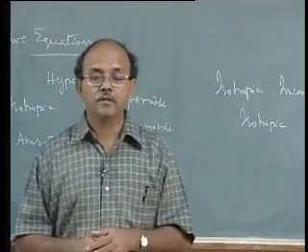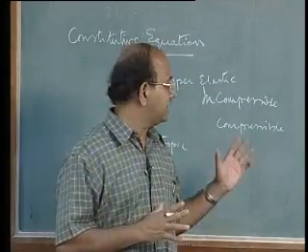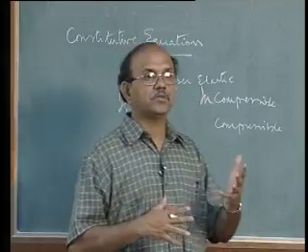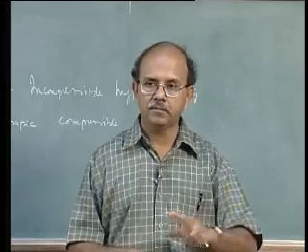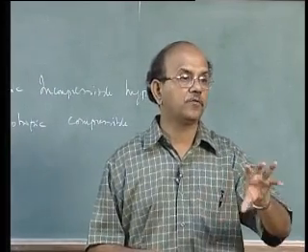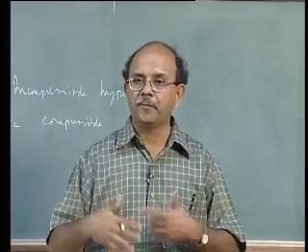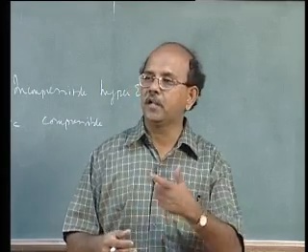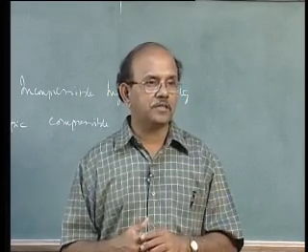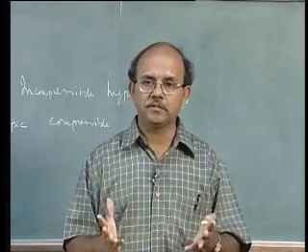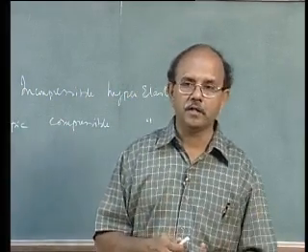If this is the case, then you do not classify this as anisotropic on a micro scale. So what you usually do is to write down an isotropic constitutive equation for the matrix material, and then take that reinforcement separately and usually put special elements which are called reinforcement elements or rebar elements. In other words, you treat them as two different materials, and there are ways of handling them in finite element analysis.